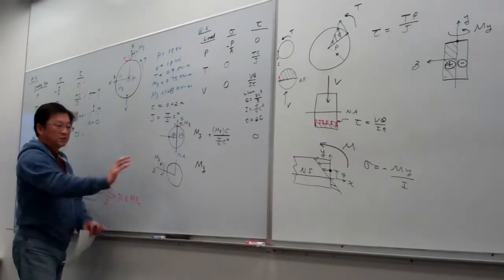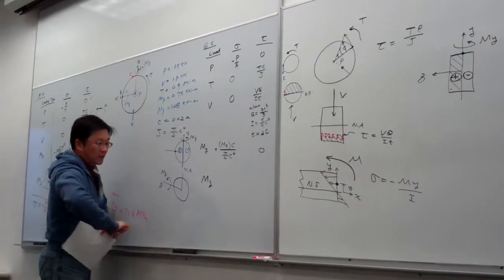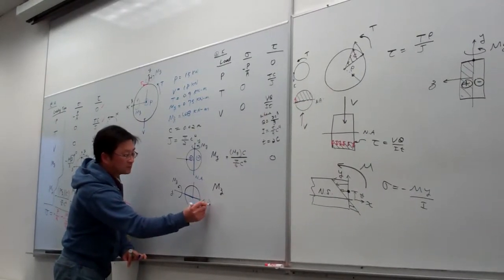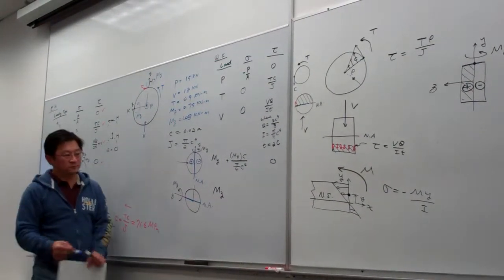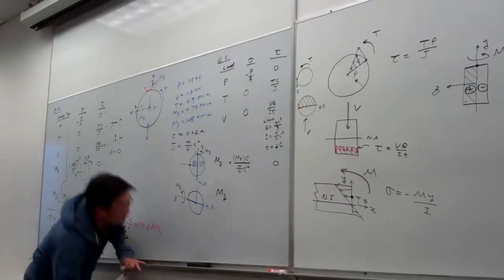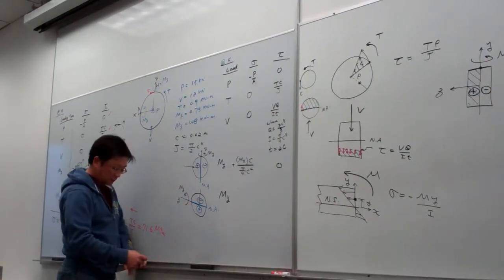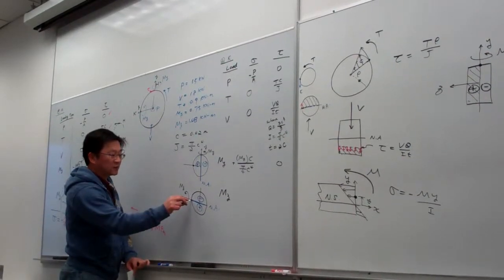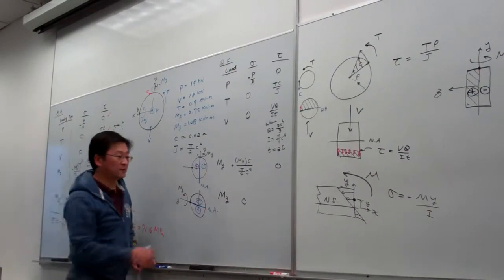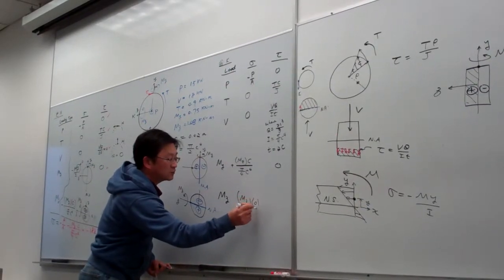So M_z basically is like this. This is the neutral axis about which the bending applies. So this is our neutral axis. And so for this case, the top will be in. Right away you can tell the point H is here, that is on the neutral axis, so this will be 0. Basically here that's 0 because of M_z multiplied by the distance to the neutral axis.